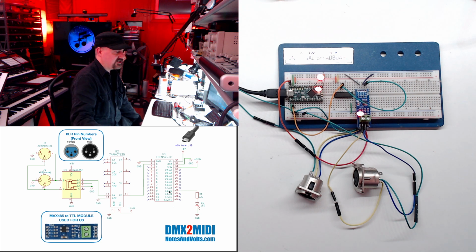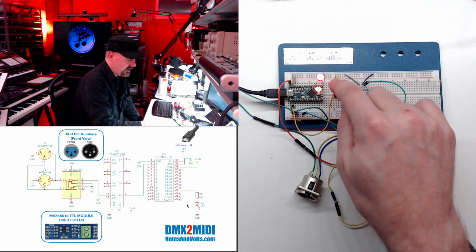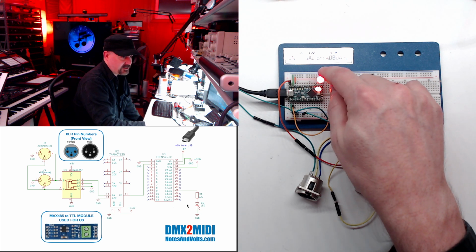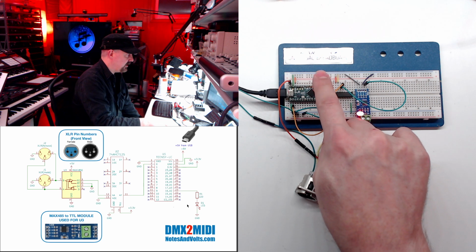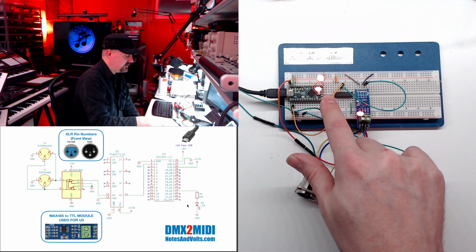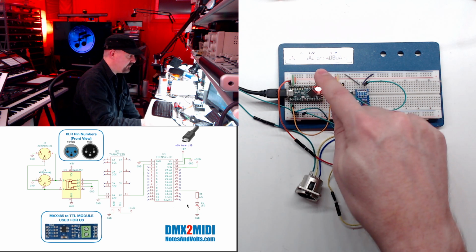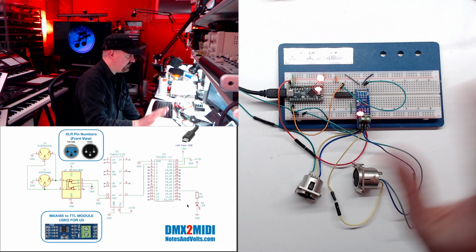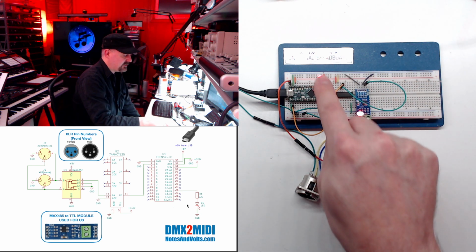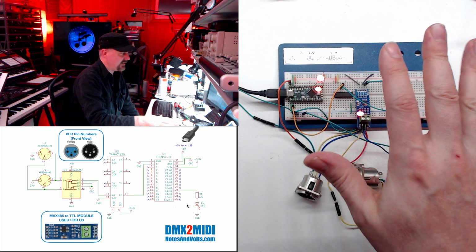So there's only one more part of this circuit, which is our little indicator LED. So I'm taking a wire from output 16 on the Teensy into the LED, and then through a current limiting resistor, which is 220 ohms, into ground. And that's going to allow this LED to light up when this pin becomes active. So notice there's also a built-in LED on the Teensy, and that's going to give the same information as our indicator LED. So if you don't want to include these two components, you can leave them out. But I figured if you're going to put this in a box, it'll be nice to put that LED sticking out so you can actually see that it's powered on and that it's working.